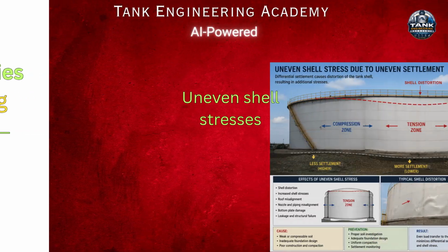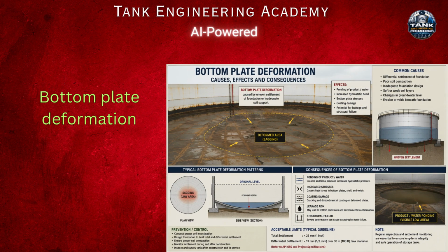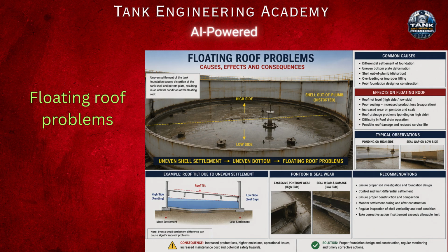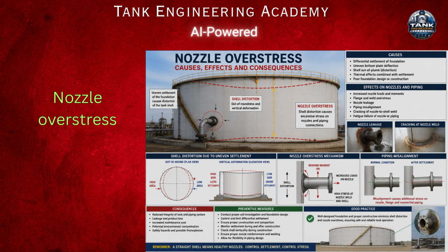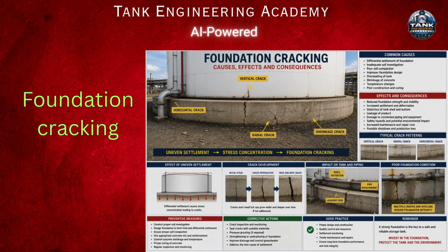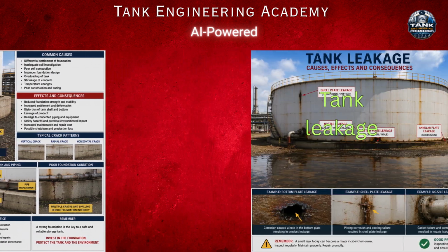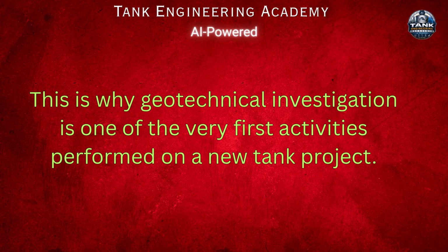Settlement can lead to uneven shell stresses, bottom plate deformation, floating roof problems, nozzle overstress, pipe misalignment, foundation cracking, tank leakage. This is why geotechnical investigation is one of the very first activities performed on a new tank project.